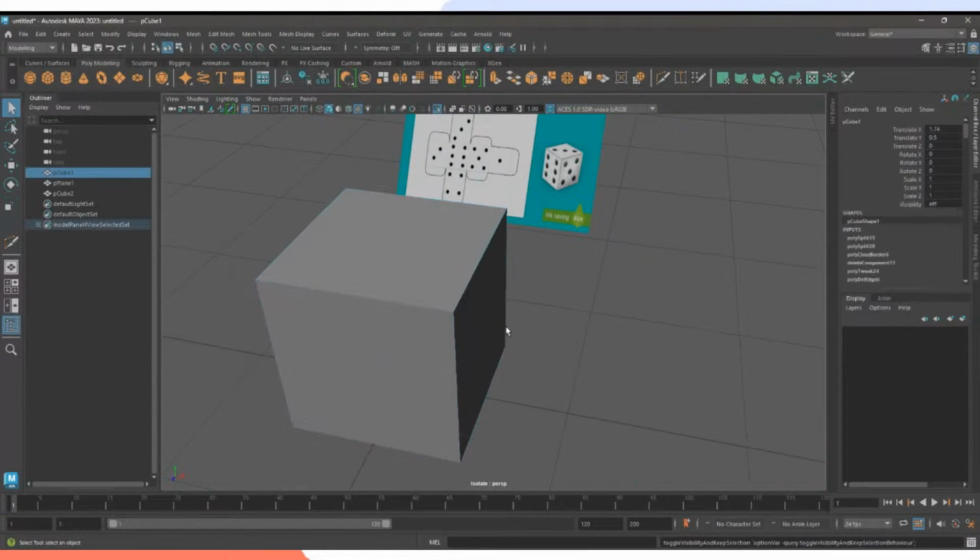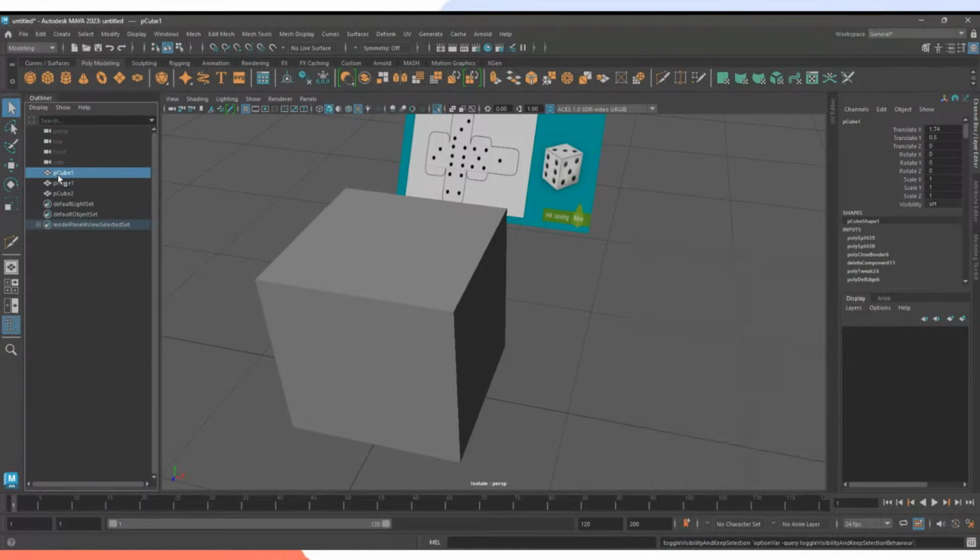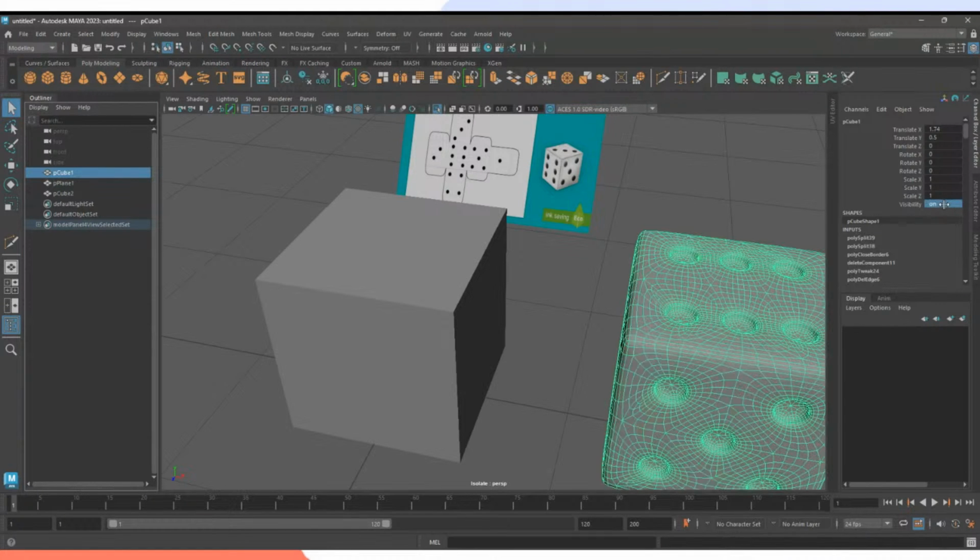Let's select that. Put that away. The way I was able to show and hide my objects here, by the way, we have an outliner. This is basically showing every object you have inside your current project file. You can press H or press H again to show and hide your objects. Oh, you can also type it.